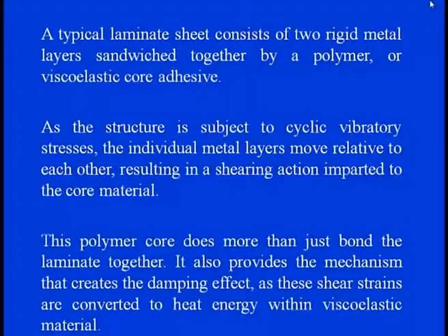This laminated sheet plate can act not only as an absorbing feature for vibration excitation, but you can also see here that it can remove heat. So we can say that these sandwiches can be framed with a polymer or viscoelastic or any similar core adhesive, and this polymer core does more than just bond the laminate together. It also provides the mechanism that creates the damping effect, as the shear strains are converted into heat energy within the elastic material.